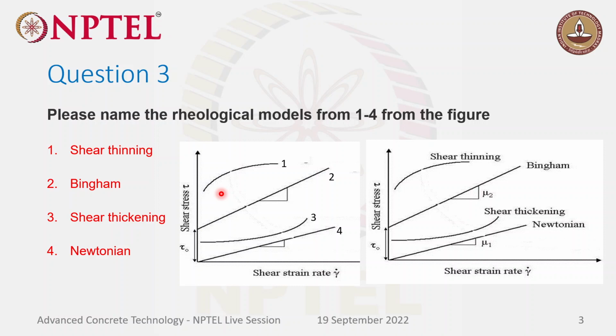But once you start mixing continuously, once you start to move the rod in it, you can move the rod easily. But once you put it to rest, and again start to mix, then you will face some resistance. Once you start mixing it, you can move the rod easily. This kind of similar behavior is observed in cement concrete, which is nothing but shear thinning.